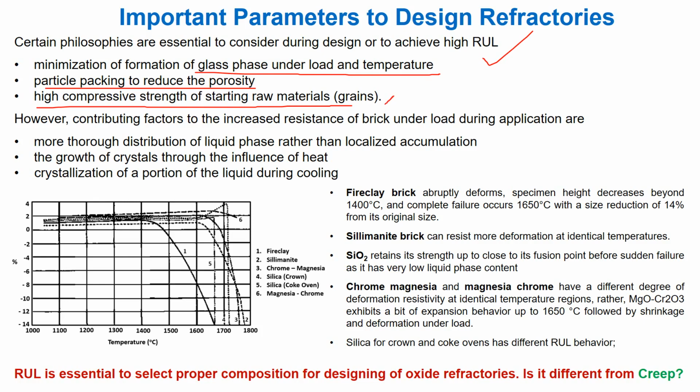However, contributing factors to the increased resistance of bricks under load during application are more thorough distribution of liquid phase rather than localized accumulation. That means it is quite obvious when the phase is forming, and if the viscosity of the phase is low, the possibility of deformation is more. The growth of crystals through the influence of heat, crystallization of a portion of the liquid during cooling.